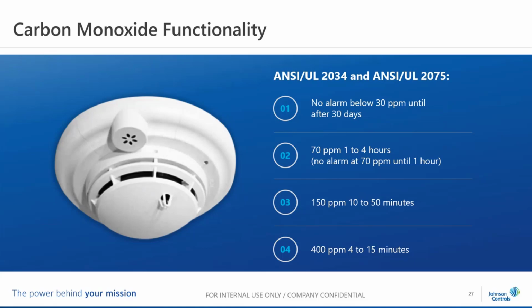So Roger, what are you driving at? What I'm driving at is with the Johnson Controls carbon monoxide sensor, I'm both a multi-criteria and a multi-sensor device, meaning you, through programming, can do both. I can make it work as a life safety device. In addition, I can write an equation that says at 20 parts per million of carbon monoxide, activate this relay.